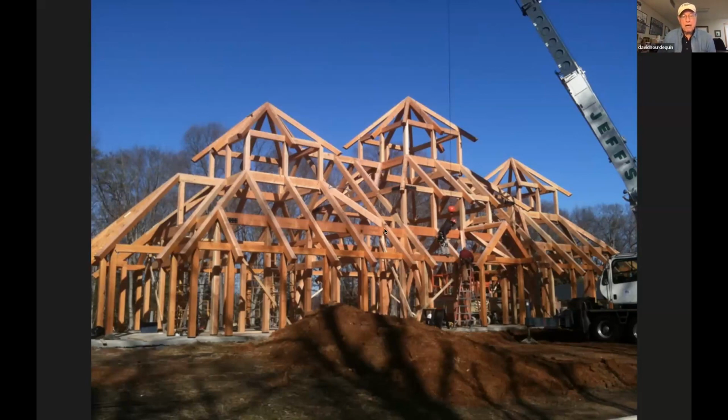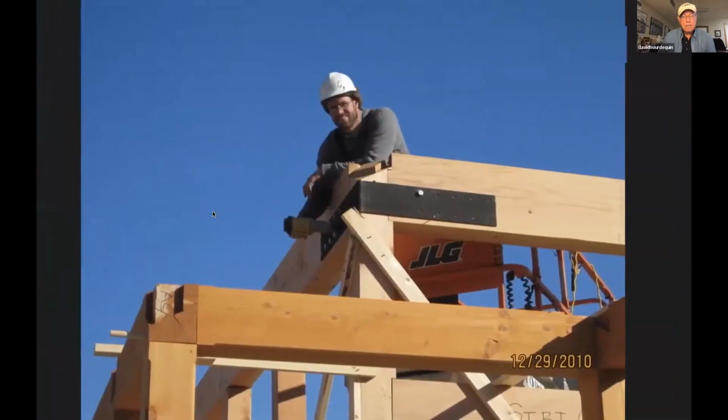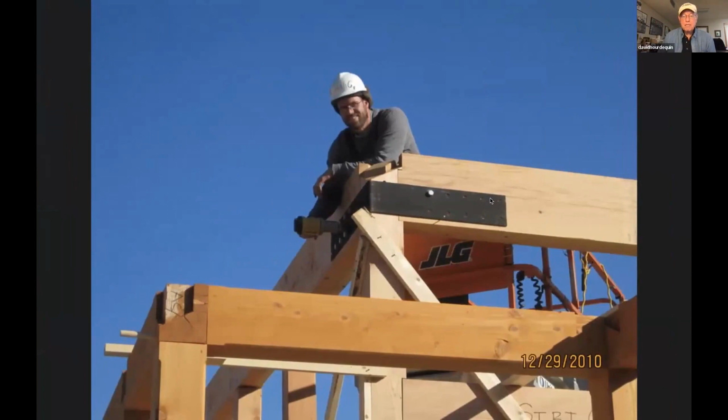And then down here you've got another tension ring, and right there is that strap that he's working on, I think. And it's a pretty hefty piece of steel. Usually you'll find that 1/4-inch plate steel can be used for this, and I'm not sure why that's so far apart. Normally, if you can, you try to get them up in the middle. I'm sure there was an aesthetic reason for this. Nothing wrong with it.